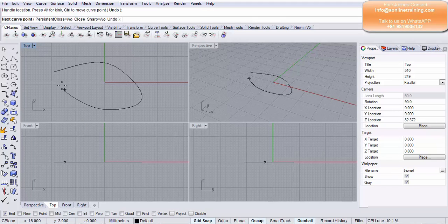And finally I come to the end point to snap. Once you are done, I would right click. You need to make sure that O snap is on so that it can properly snap at the end points. Under O snap, I have kept the end on.